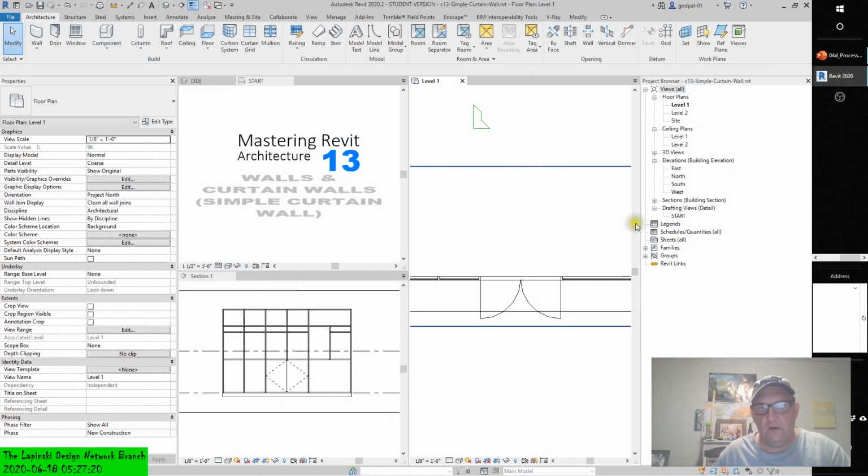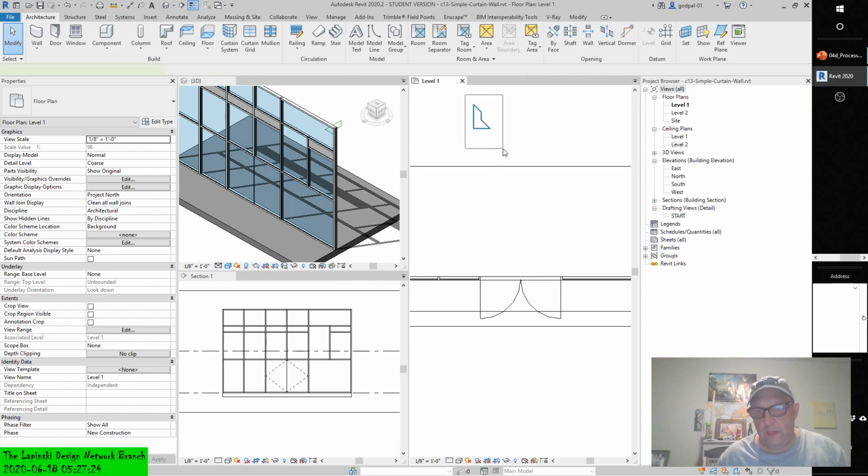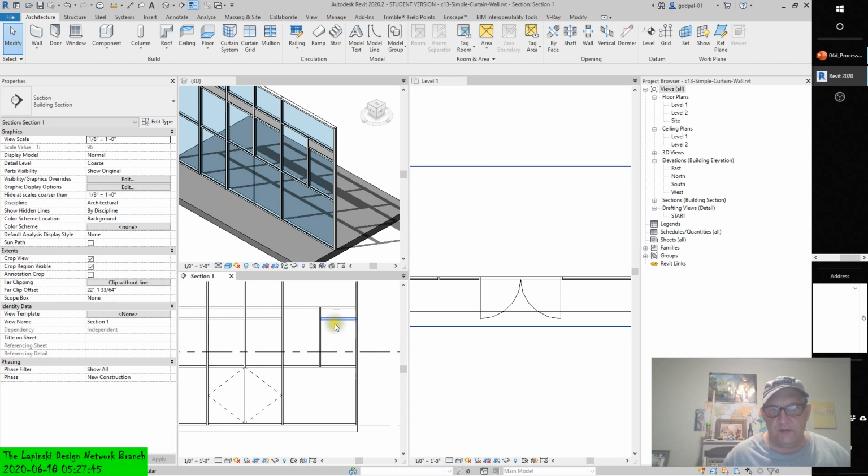All right. So now we're back in the mullion tutorial. We have to get through this. It's complex. Placing corner mullions. Corner mullions cannot be customized beyond the shapes included in the Revit project template. However, you can modify the material assigned to the mullions as well as the offset and depth dimensions in the type properties. Well, that's good.